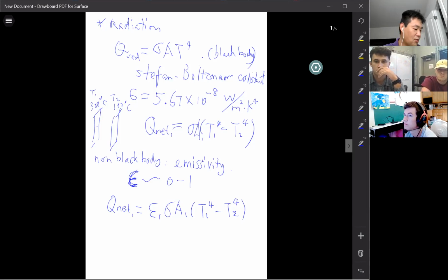For all the surfaces, they gave you a temperature range. That means they tested the emissivity only for this temperature range. For example, for highly polished brass, for temperatures between 476 to 674 Fahrenheit, the emissivity is between 0.028 and 0.031.